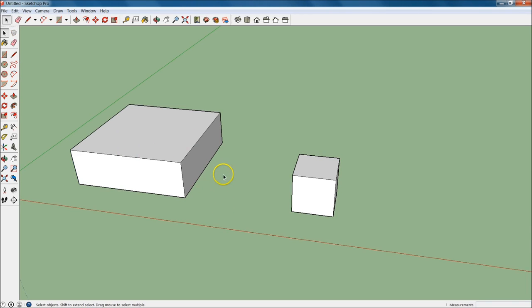But if I wanted to just have a little bit in there, if I start from the bottom right and move up, you'll see that my box is this dash line. The marquee is this dash line. And what that'll do is select everything that any piece of that component or part touches. So if I let go right here, you'll see that this surface was fully selected even though the whole surface wasn't within that marquee.